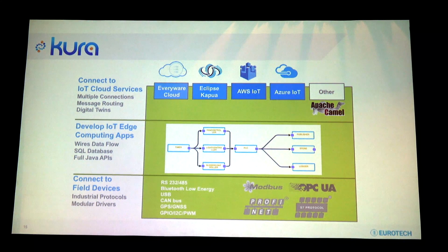If you have a very specific thing you need to do, what happens to us frequently is we go to these industrial guys and they say, well, we kind of use Modbus, but it's our own version of Modbus, right? And then they pull the engineer out of the closet who's been working there 30 years and he has his custom stack of software and says, okay, this is how it works. Well, then you can write your own driver level to do the communication.